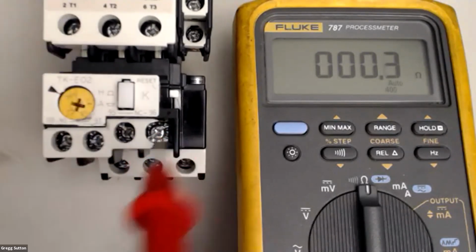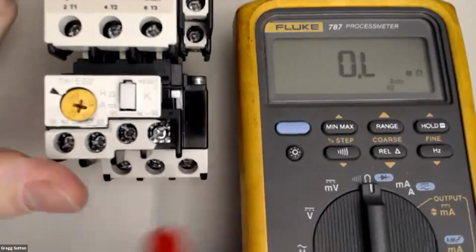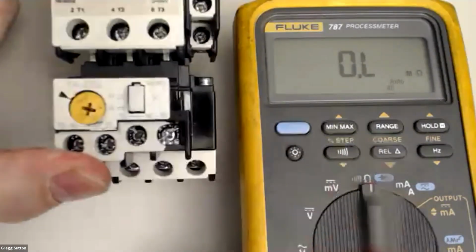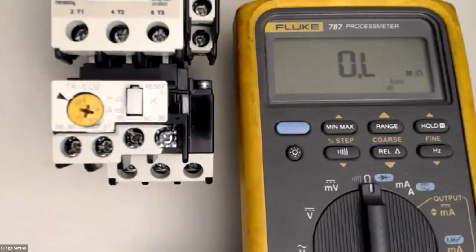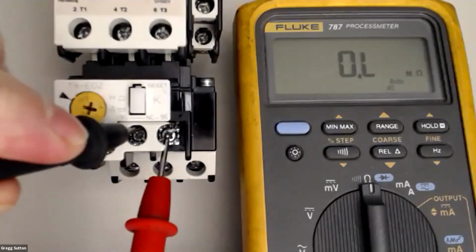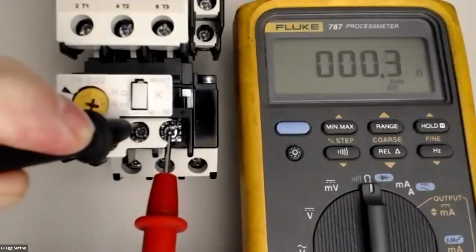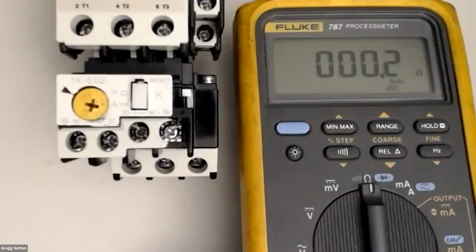Yeah, that's right. Now, what if I push this reset, this trip button down here? It's a test trip. Our overloads had tripped because of too much current. Now, what should I see here? Hopefully they should pop open, so the resistance would be OL, I think. Really high. Let's see if that's true. And that's right. And if I hit this reset button, they should go back to their normal state. There they are. Right.